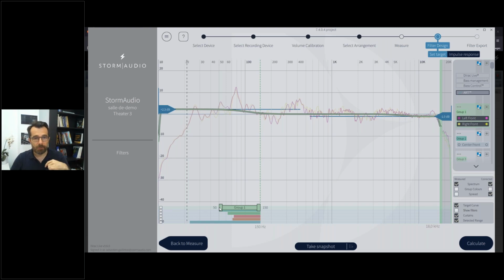But as you know, in the room, you are not measuring the near field, you're measuring the far field, meaning that you take into account the room gain, which translates into those frequencies that you get here, which could also be the result of the position of the speakers emphasizing the low frequency. So that's not because the speaker is capable of doing it, it's because at a certain pressure level, it can do that. So this is when you start to look at your data sheet and you start to adjust that, okay?